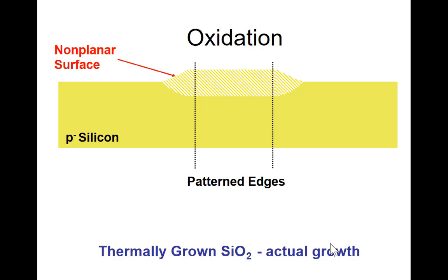Okay, and in the 0.5 process, this is typically the silicon dioxide that we use around the transistors. So this is using the growth, thermal growth. You put your silicon at a high temperature, exposed to oxygen, and then it grows oxide.